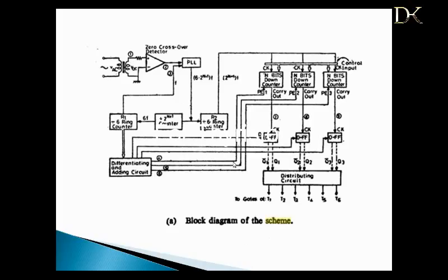The digital PLL is used to multiply the main frequency by 6 times 2 to the power of n plus 1, consisting of a divide by 2 to the power of n plus 1 counter and a divide by 6 ring counter.